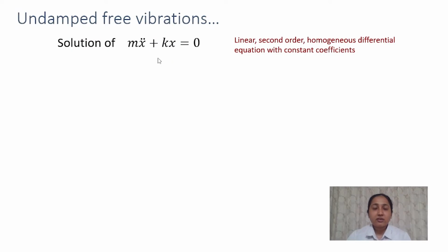So we have our equation of motion. This is a linear second order differential equation. It is homogeneous and we have constant coefficients. To solve this, calculus theory tells us that the general form of the solution is e to the power s t. If this exponential function is a solution of this equation, then if we substitute it in, it should satisfy the identity. So let's do that.